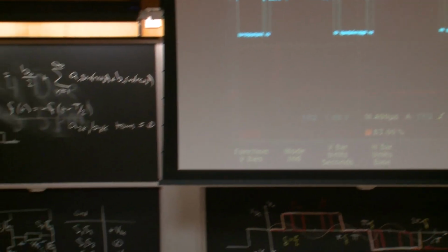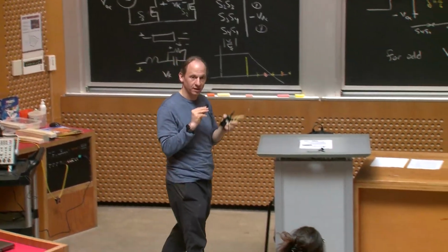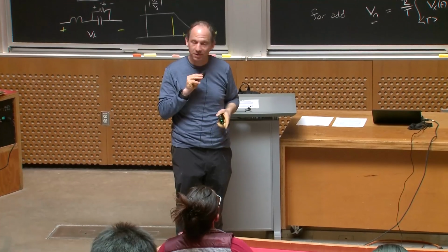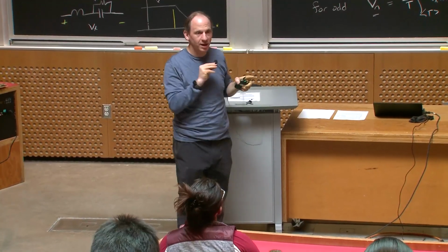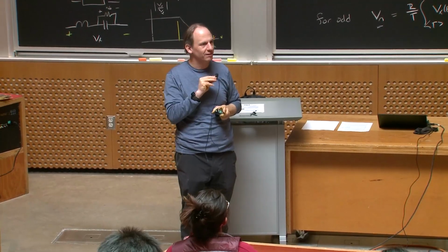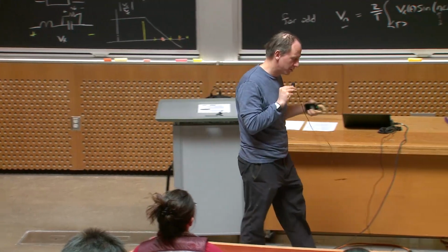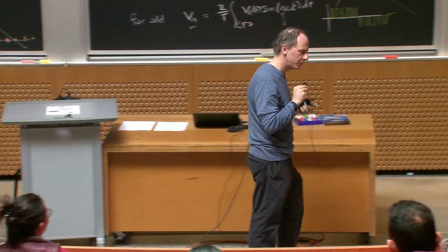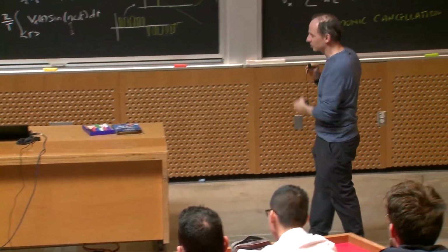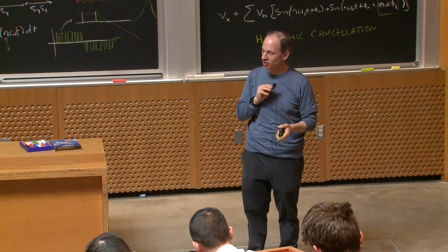Thanks. So I guess what we've seen today is harmonic elimination, where we introduce extra pulses carefully timed. We've also seen harmonic cancellation, where we take multiple waveforms, shift them, and add them up to kind of murder the harmonics we don't like. Those can both be used together. What we'll start seeing next time is other ways we can play this harmonic cancellation or elimination game, with more sophisticated circuits.